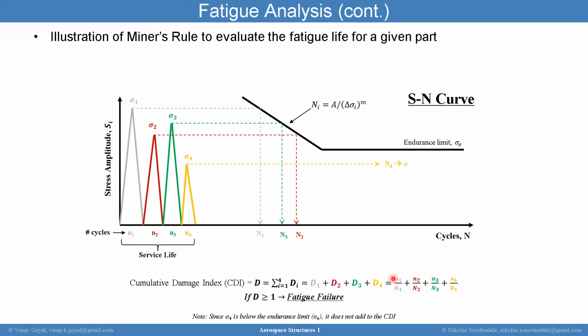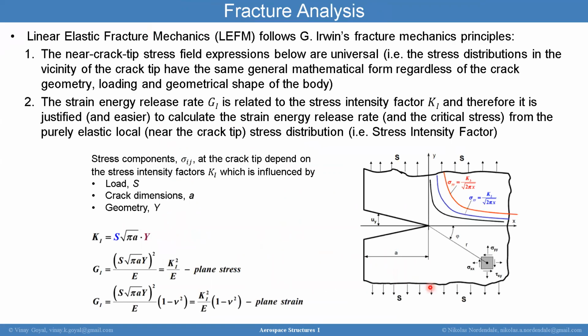I'll add this together, and I want to make sure that the damage is less than 1, and if you apply the factor of safety or fatigue scatter factor of 4, then it will be less than 0.25.